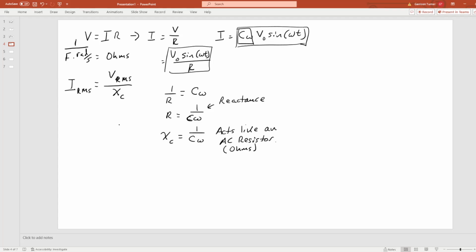It behaves like resistance, but because my signal is sinusoidal and my reactance depends on omega, my reactance can change based on the properties of my circuit, not just the physical properties of my resistor. Whereas my resistance would be a set value over most temperature ranges. If the resistor got really hot, of course, the resistance could change.